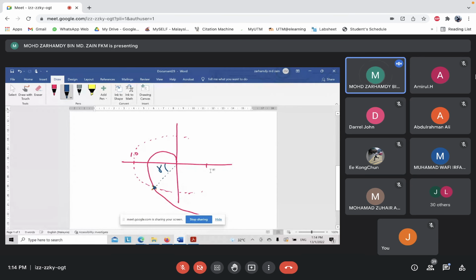Okay, can? Now, take this line as a reference. Then we take here, from here. This is the angle gamma. Gamma is the phase margin. So later we will see how many angles. No need to use a protractor or projector. You will get the exact value. Each angle is 10, represented as 10. So 10, 20, 30, 40. So for example now maybe 50. Like that, you directly get it. Got the picture?